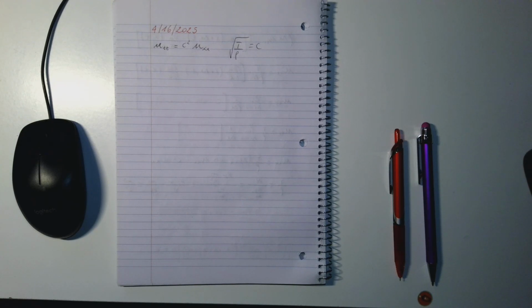So I would say that the main goal of the modal analysis is to have equations that are related to each degree of freedom that are not coupled to each other. If you remember, when we solved a 2-degree of freedom system for the first time, we ended up with two differential equations that were coupled.